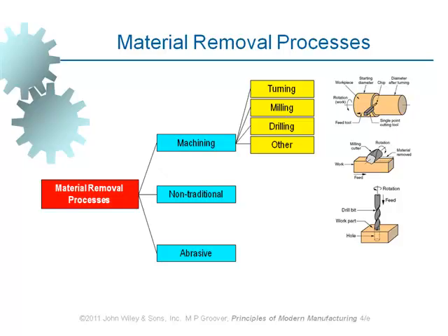Indeed, it is stationary. However, it makes a motion of feed. The workpiece is on the table, and the table makes it move, which is called the feed motion, and the cutting tool, which is rotating above it, can take the cut.